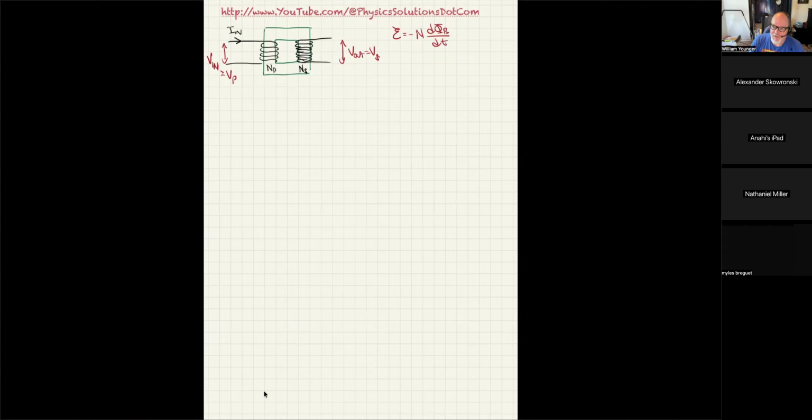So to make this transformer as close to 100% efficient as possible, it's best to not use a big chunk of solid iron, but rather use a bunch of plates of iron, sort of assembled like a jigsaw puzzle to some extent, except much more regular shapes, and then laminated together.